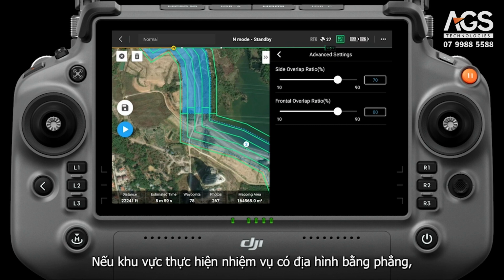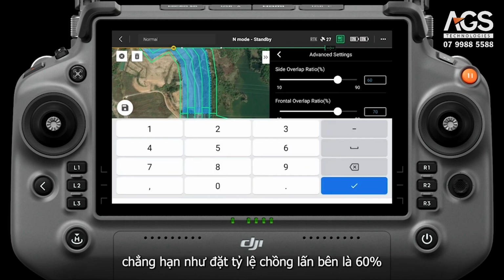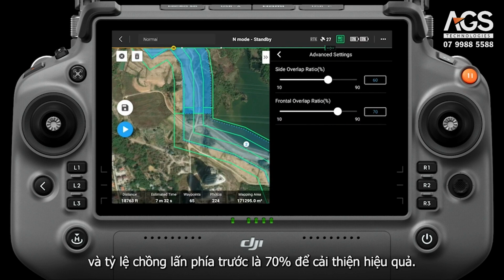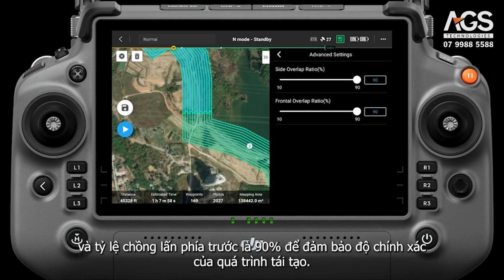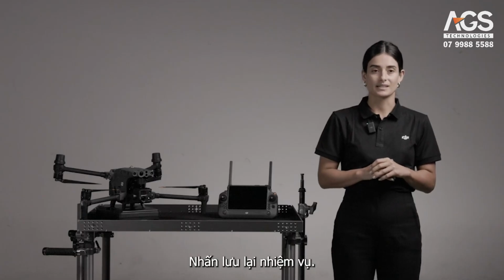If the mission area is flat, the overlap ratio can be appropriately reduced, such as setting the side overlap ratio to 60% and the frontal overlap ratio to 70% to improve efficiency. If the task area fluctuates greatly, it is recommended to increase the overlap ratio. For example, set the side overlap ratio to 90% and the frontal overlap ratio to 90% to ensure the reconstruction effect. After setting the parameters, save the task.